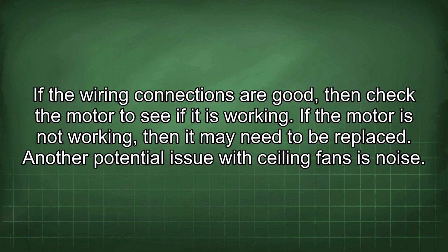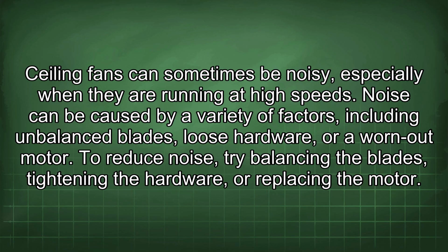Another potential issue with ceiling fans is noise. Ceiling fans can sometimes be noisy, especially when they are running at high speeds. Noise can be caused by a variety of factors, including unbalanced blades, loose hardware, or a worn-out motor. To reduce noise, try balancing the blades, tightening the hardware, or replacing the motor.